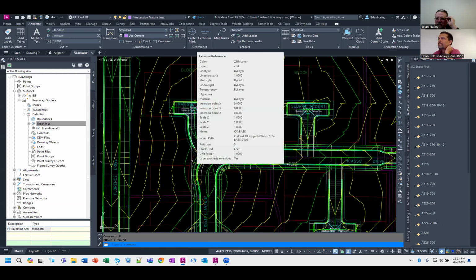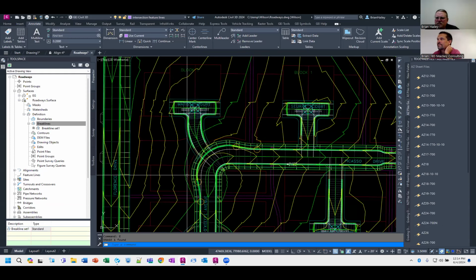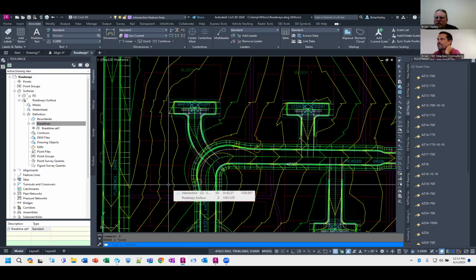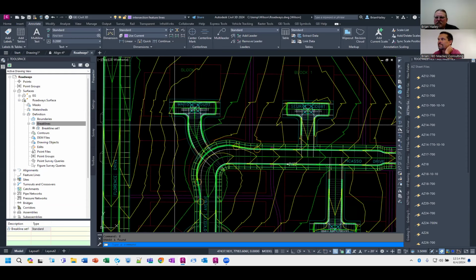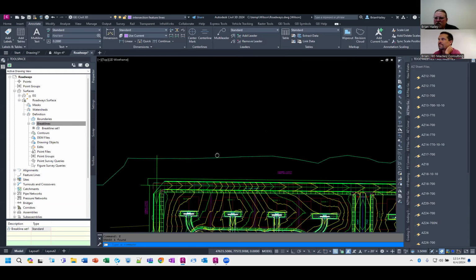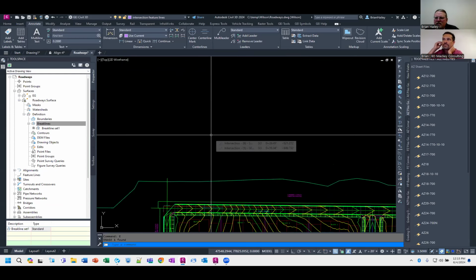So what else takes time? Setting up the sheets, your symbols, make sure you have a library with all of your symbols in it. Another thing that takes a lot of time is just drawing lines. Setting the layer, drawing the line, making sure it's the right line type.